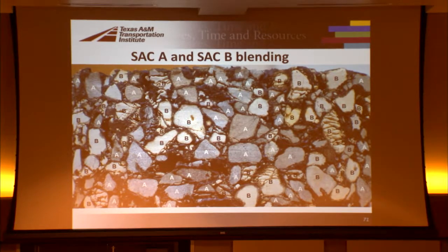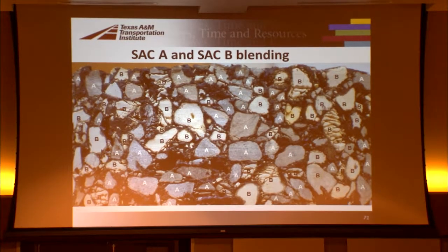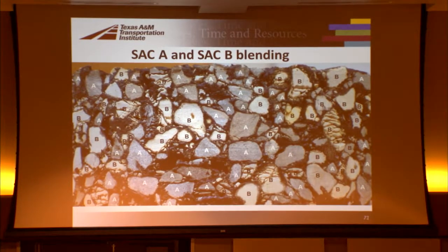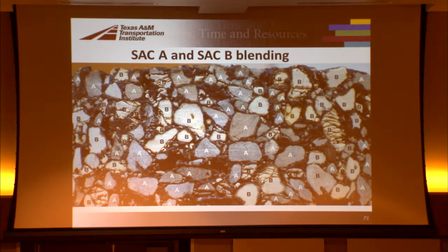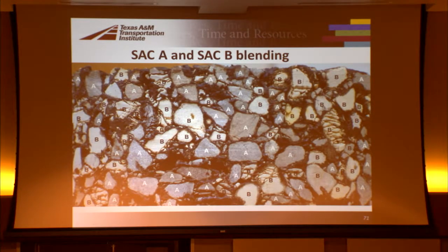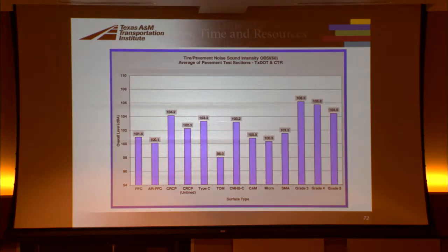We don't recommend blending. This is actually a slide from Mike Arellano. In Fort Worth, it may be a little better because of the higher quality limestones, but this is from a South Texas source. When you start doing this blending, San Antonio did this differential wear course, you can see here the B's are being crushed while the A's are still fine. So for high traffic, I'd say stay away from blending and just stay with the A aggregate. Basically, you're doing thin mixes, which cost more per ton, but because they're thin, you can pave more.